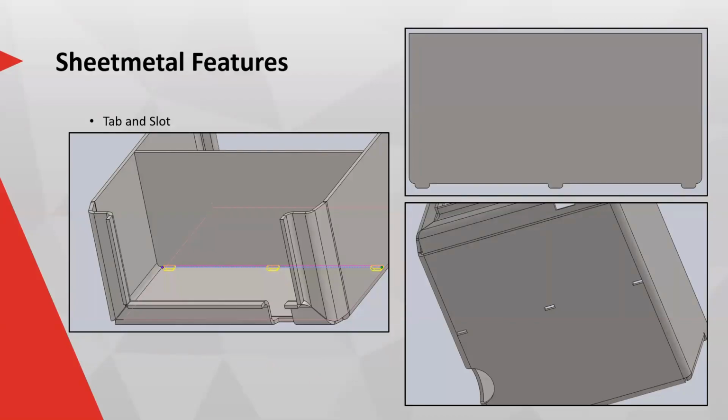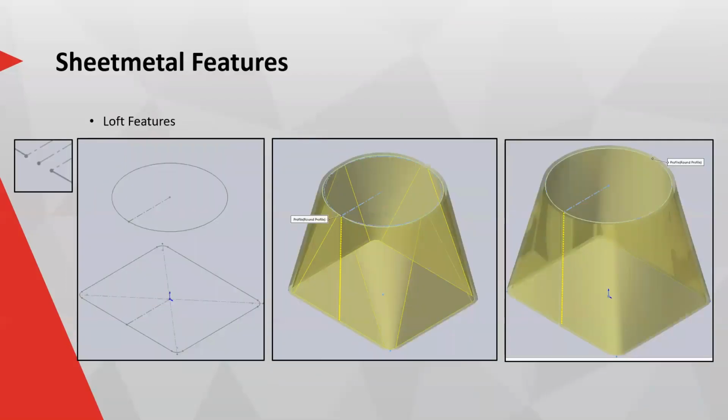Okay. Next, we're going to have a look at loft features. So loft features are quite popular in the HVAC industry. There are two sketches, generally a square to round or various square shapes or octagons, or it's just between two sketches, and it will actually automatically generate the geometry. So you'll see for these two examples here, I had added in a few nice examples.